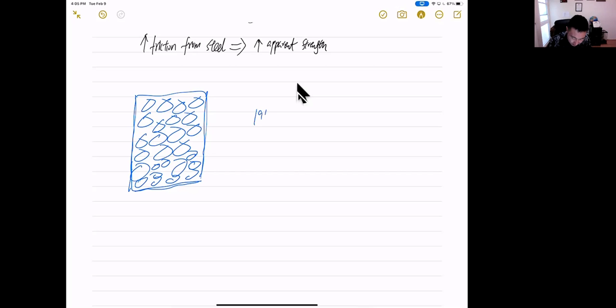So this is 1917 times 1 plus absorption capacity. 1917 is the dry rodded weight, that is the weight of aggregate in oven dry condition, times 1 plus AC. AC is absorption capacity, which is defined by W_SSD minus W_OD, divided by W_OD.